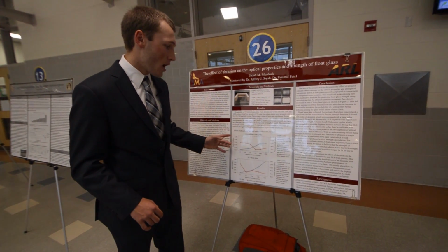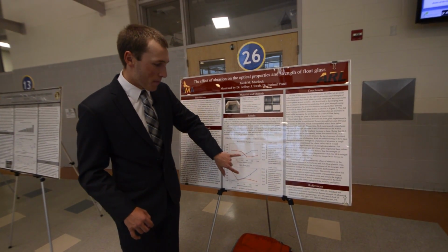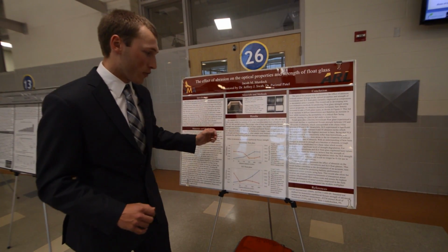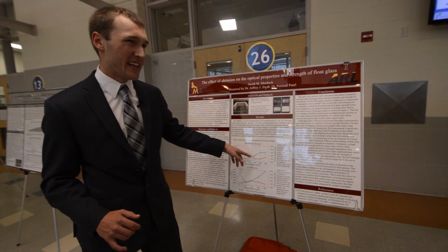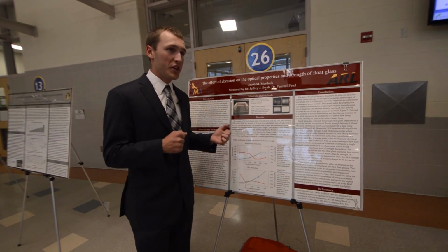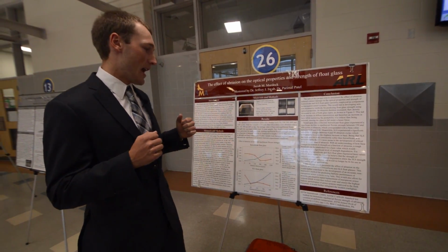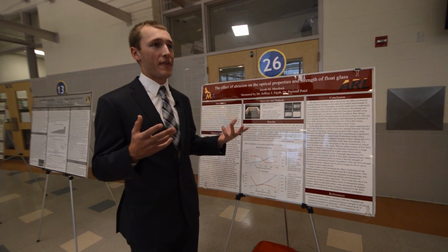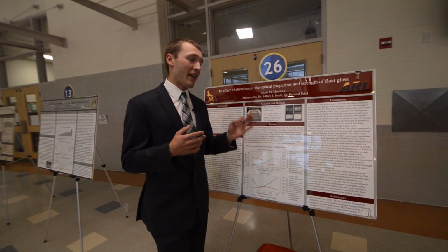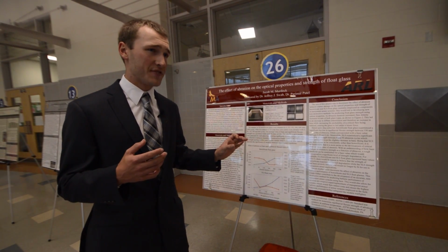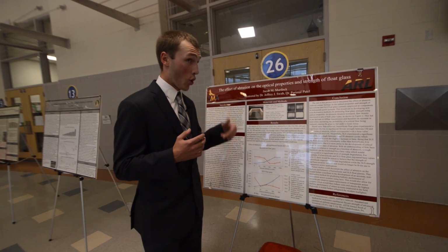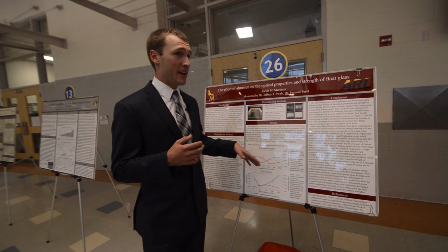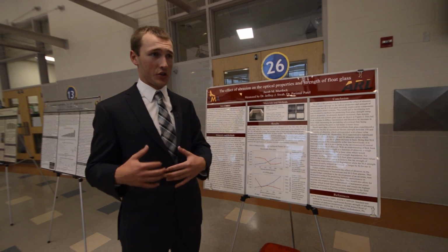At the same time, we recognize that at the moment that the glass fails and you reach this drop-off, if we're able to isolate the value of haze that corresponds with that drop-off, we can use that haze value as a quality control standard for manufacturing purposes. Therefore, the manufacturer can be alerted that if any of the glass they're manufacturing has a haze value registered at that value or above, there's statistical reason to believe that the strength has been degraded a significant amount and it should be taken out of circulation.